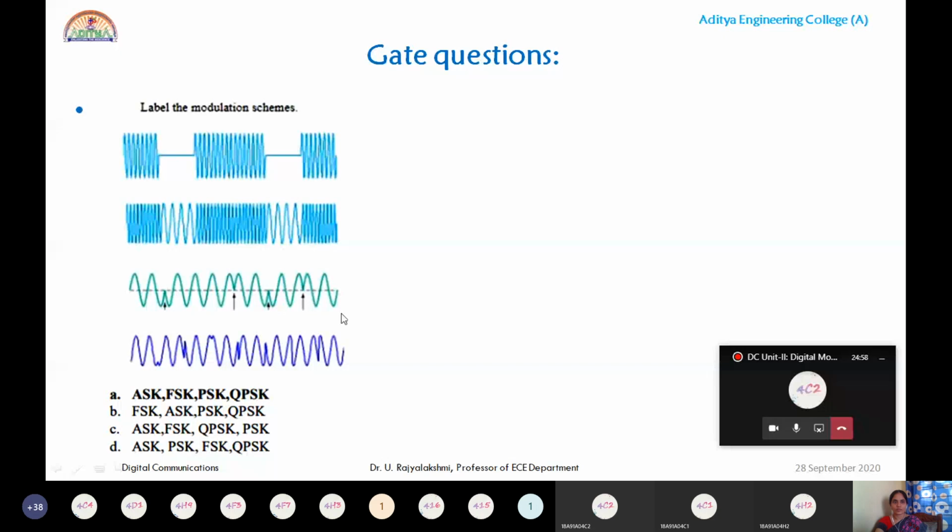Ma C2. Can you tell me the general expression for PSK? A_c cos(ω_c t) for input 1, ma'am. Okay, that's why you got the same as the carrier. A_c cos(ω_c t + π) for 0, ma'am. Okay, that is nothing but minus A_c cos(ω_c t) for data 0. Like that you got the corresponding response.